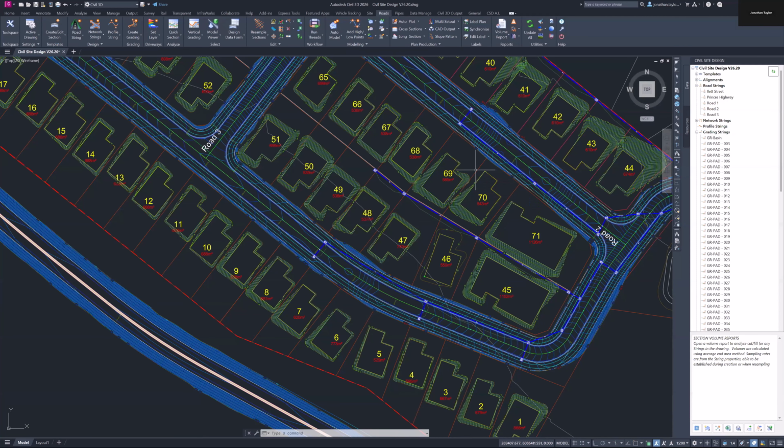So essentially everything that I do with quick section is stashed within that polyline. If I delete it, I've effectively lost all the settings that I made in there, but it's all about checkboxes. I'm going to run this again. Great bit of layer control there. Give the thing a width, old school, 0.5. There we go. And we'll use this polyline. So we'll run quick section.